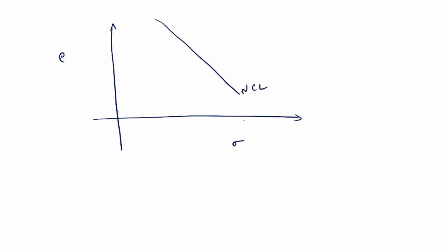As the effective stress is increasing, the void ratio will decrease on a straight line on the log sigma axis. But after reaching some point, if you reload it, meaning you are removing the stress, what happens? It will again rebound. It will swell.